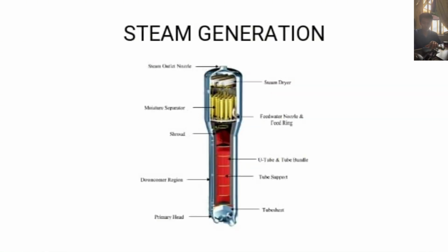The second type of component in nuclear power plant is the steam generator, a boiler, a form of low water content boiler similar to a flash steam boiler. The usual construction is a spiral coil of water tube arranged as a single or monotube coil. The circulation is once through and pumped under pressure.